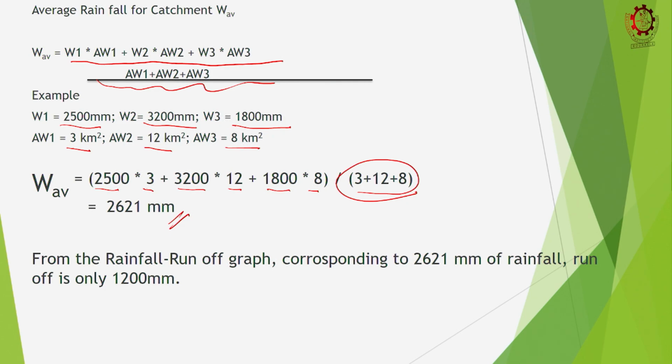Now, I told you that all the rain that goes into this will not come into my diversion point. Why? Because the water will be evaporated, trees will absorb it and leaves will transpire it to the air, and some water will go to the groundwater, right. Some water will be utilized by the people, animals and so on. So, only a portion of it can come to my diversion point.